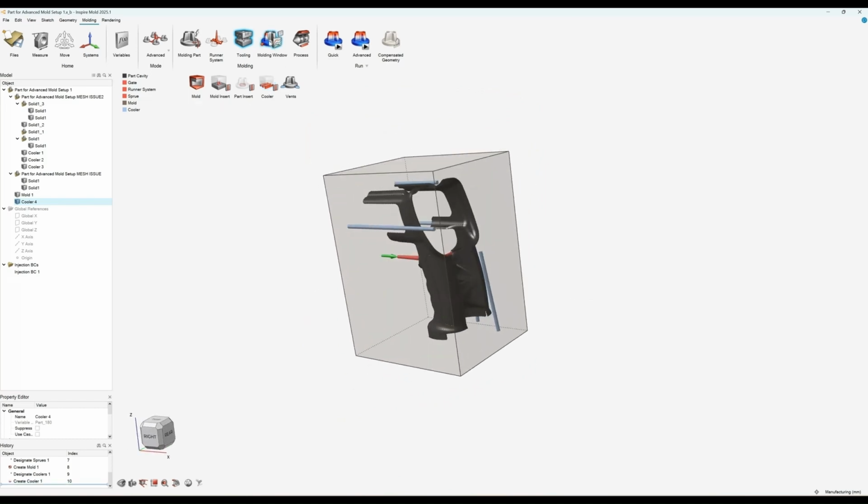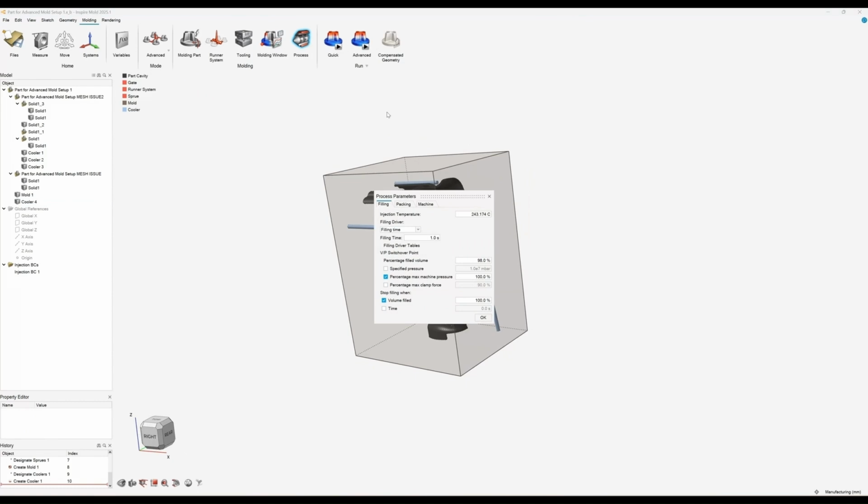we've looked at the molding window, so I won't look at that, but then you've got your process parameters. Obviously, being able to iteratively change these parameters to influence our results can be just as important as the method itself in order to get good results, like increasing our packing time, maybe changing the fill time, all these machine settings. If you can iteratively change those to get better results, obviously that's really, really important. So we can play around with our process parameters.